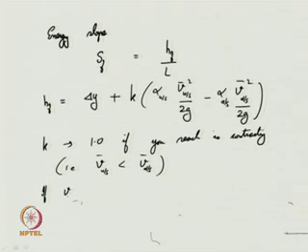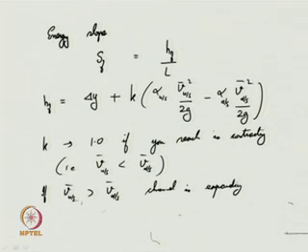If V upstream is greater than V downstream, the channel is expanding, and you have to take k equal to 0.5. Many scientists have obtained these experimentally or through analytics, so we will just incorporate them in our analysis here.